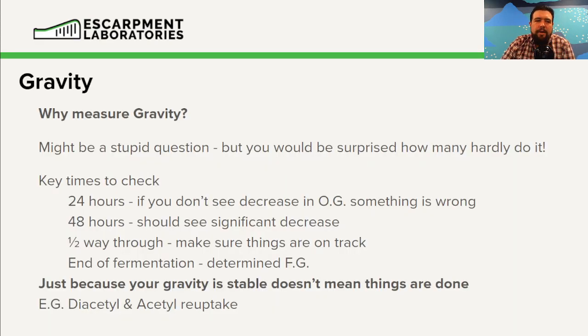Now, another one that might sound kind of silly, but gravity. We obviously need to be checking our gravity. The thing I want to emphasize here is when we should be checking our gravity. Key times to check, in my mind, would be 24 hours into ferment. If we do not see a decrease in our gravity within 24 hours, we know something has gone wrong.